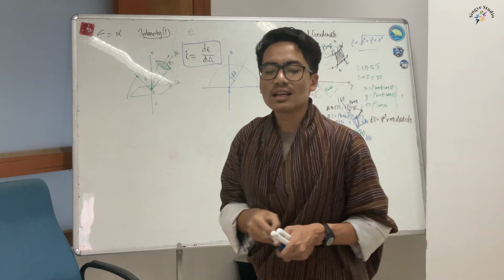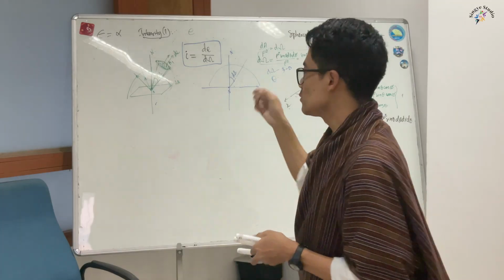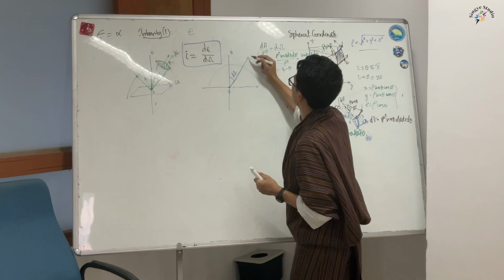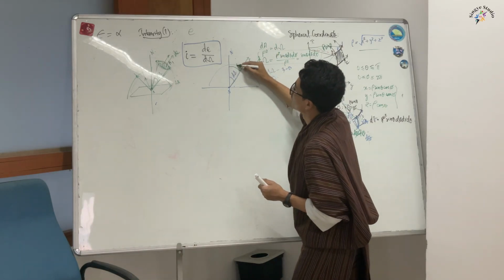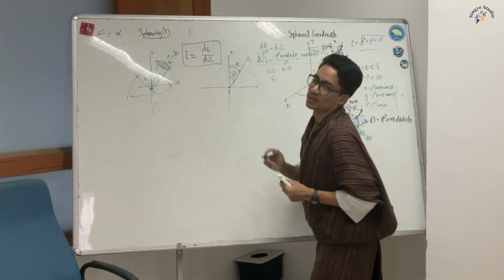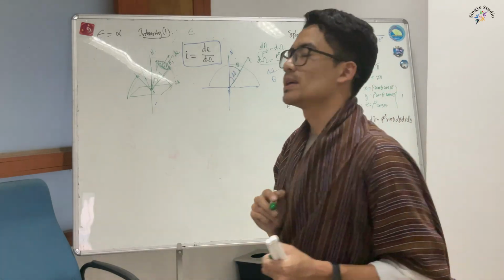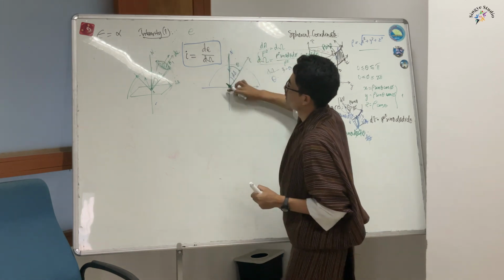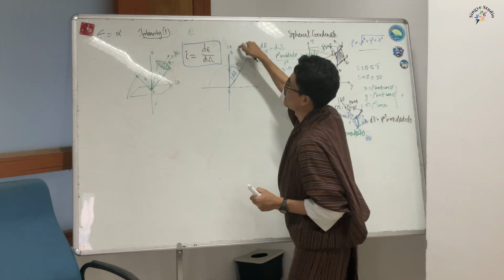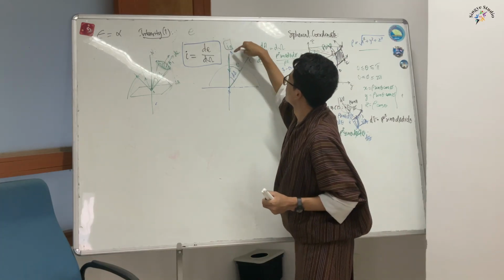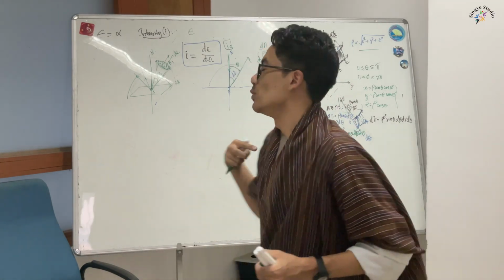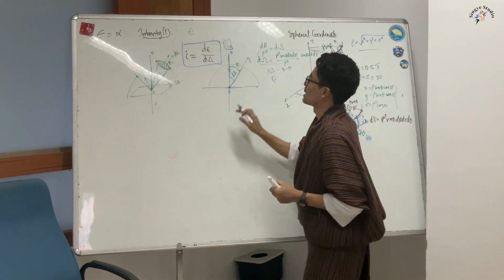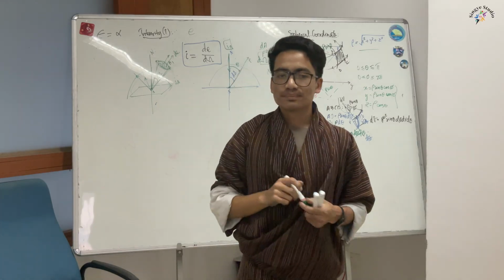In 2D I get the angle theta, that's the zenith angle. So in 2D I'm saying this is the intensity of radiation that I found in the direction which is theta angle away from the normal. But the only value that I know is the one that is along the normal, which I call IN. This ray is along the normal of the plane, and this plane is the surface area of the emitter plate.